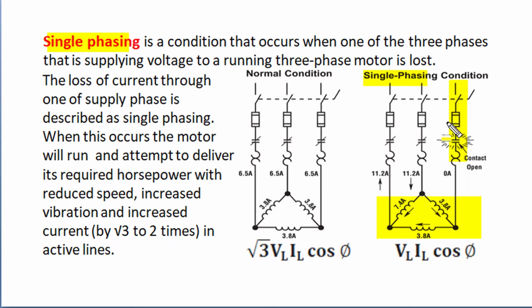with two supply lines supplying electricity to a delta connected induction motor. Now to deliver the same mechanical output, the motor draws the same electrical input, and when in place of three-phase supply, it will have only single-phase supply between two lines with line voltage VL, the motor will increase its line current to maintain the same amount of mechanical output, and sometimes with such single phasing condition, the motor power factor also decreases.